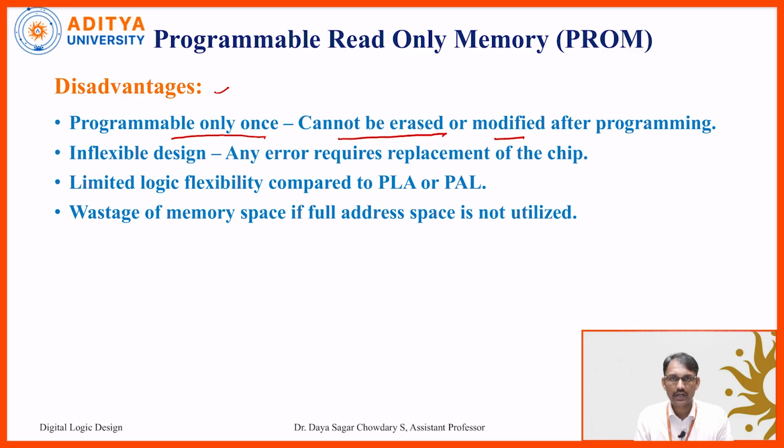So after programming the particular PROM, we cannot change whatever the inputs or whatever the application in the particular PROM. So, inflexible design, because any error requires replacement of the chip. If the program contains any error, after dumping the entire equation in the PROM, we cannot erase it. So simply we have to replace the entire chip. This is the drawback for the PROM.